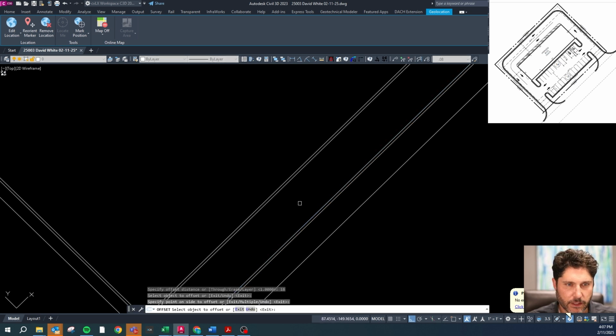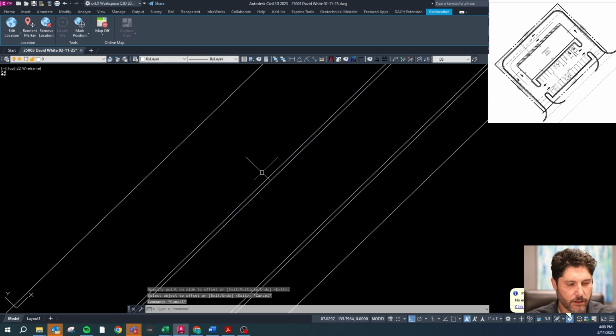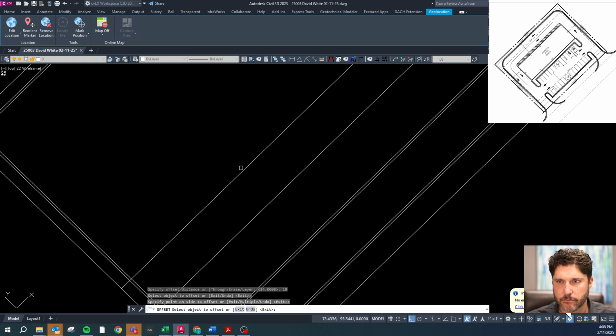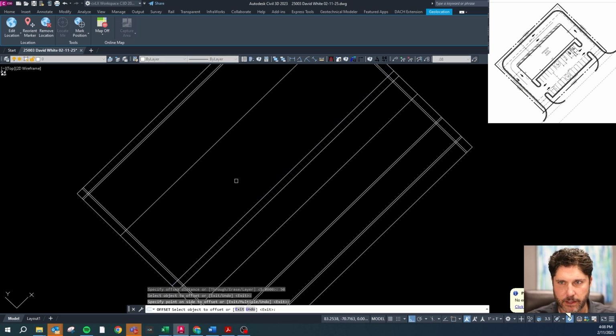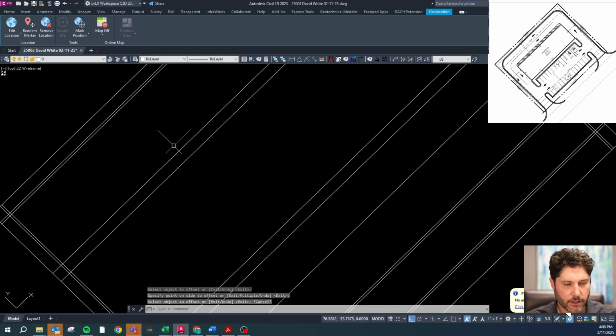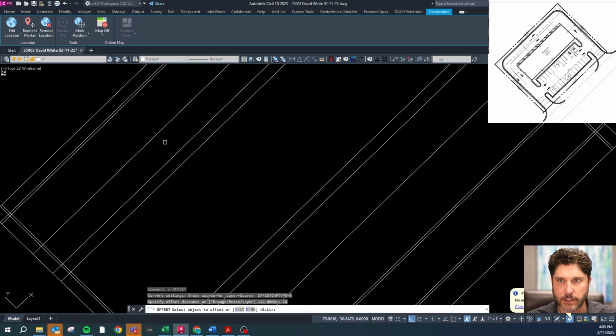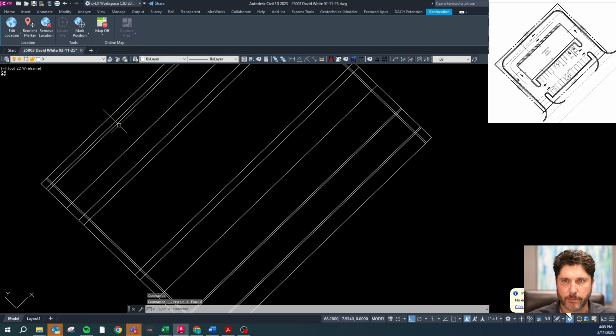So I have 18 feet for the parking spaces, 24 feet, another 18 feet. That's dimensioned as a 5-foot sidewalk, and the building is 50 feet deep. Looks like another 5-foot striping, and a 12-foot drive aisle and an 18-foot drive aisle. So that's actually not 1 foot off. It looks like it's maybe 2 feet off.